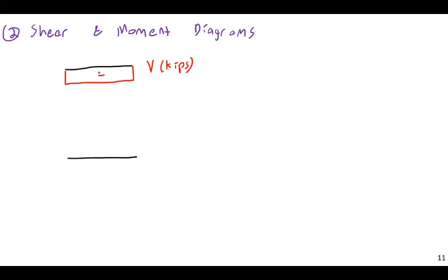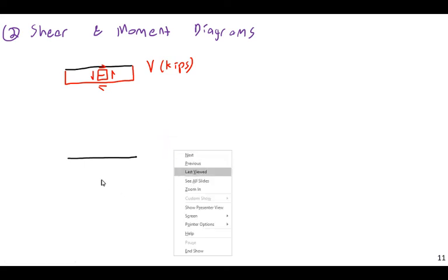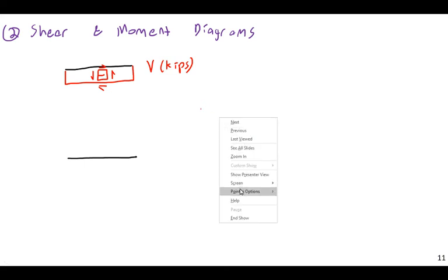So this is negative shear, and we'd have arrows like that, and to balance it, like this here. Then for the moment, and we do know this is 10 feet long, and I should complete the diagram by saying this is negative 50 kips.